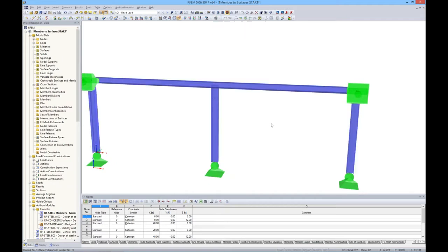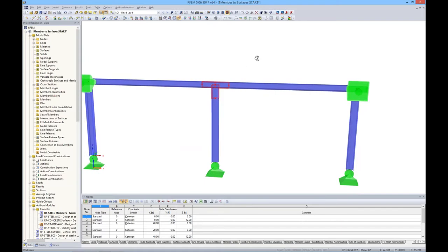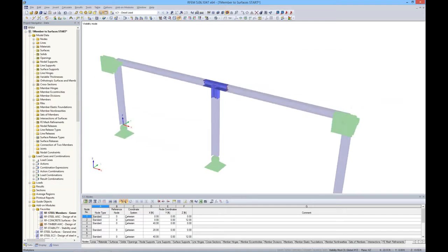So I'm going to go ahead and render it again. And I'm going to select these, and the selection is just similar to AutoCAD. If I drag from left to right, it will only grab what's in that box. If I go from right to left, it will grab everything that box touches. So for this case, I'm just going to select here, and I'm going to choose Visibility by Selected Objects. So now I can no longer select anything other than these 3 elements that I specified before.